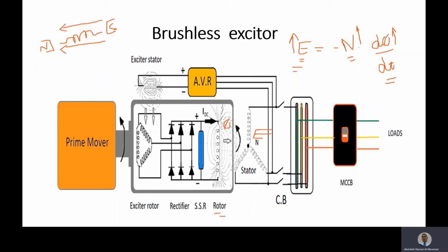So if we start to rotate the coil inside the flux, now it is at a zero angle, for example, okay. Suppose now at zero, no flux will be intersecting the coil. Once you rotate the coil with an angle, for example, 30 degrees, some of the flux lines will be intersecting the coil and the voltage will be produced in the coil.